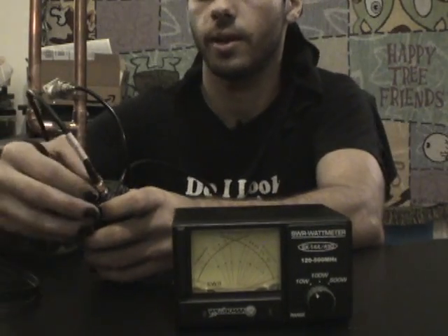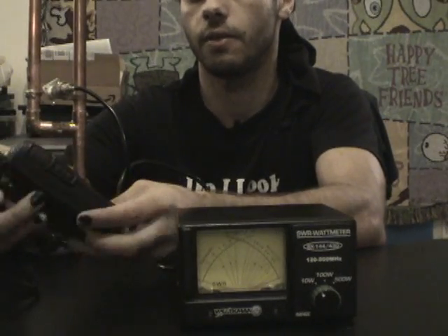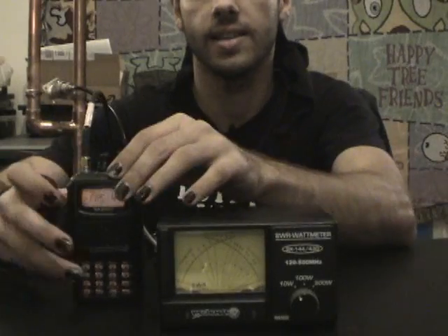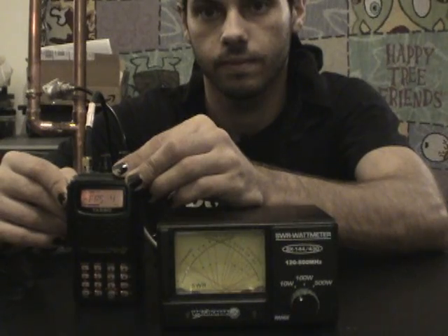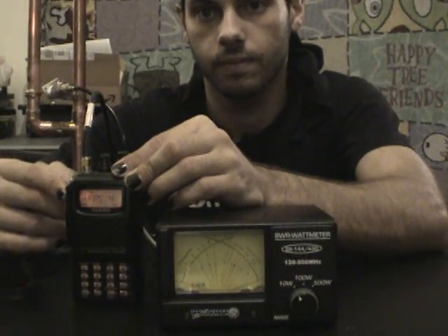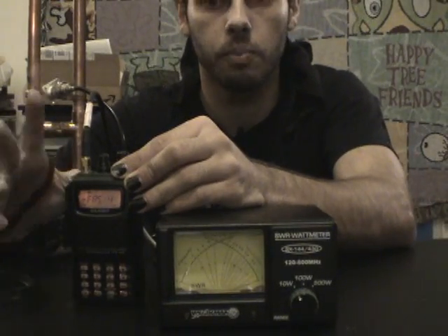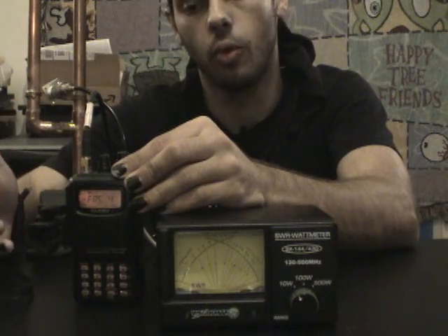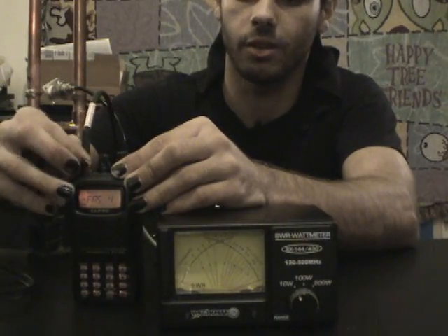Now I'm just going to turn my radio on real quick, and I'm going to lock the backlight on for you so we can see, and we're going to take our power output down to a legal FRS limit. Now hopefully we can see, as I transmit, this should give off a pretty decent SWR. Now if you notice, we're doing about 1.1 to 1 SWR, which is pretty good. Anything above, I'd say 1.5, you're getting kind of suicidal with your antenna.